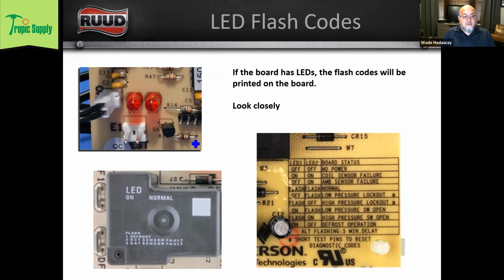A lot of times, especially in relatively warmer climates like you guys have in Florida, the outdoor coil itself might defrost in off cycle, meaning that it might be warm enough, or you might have enough sun exposure on the house, or whatever reason, that it might never actually go into defrost.